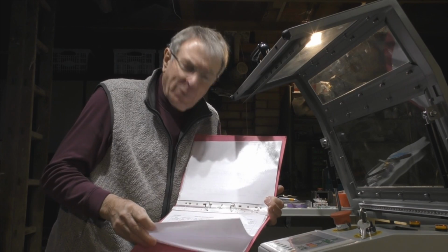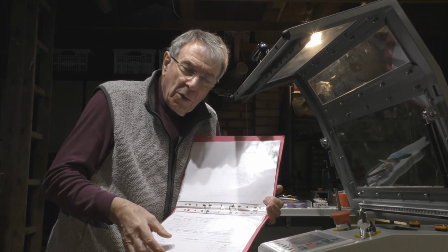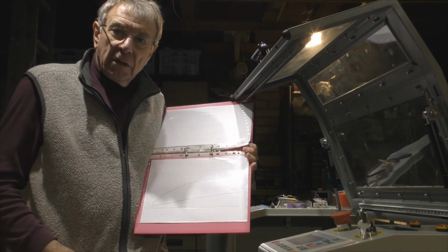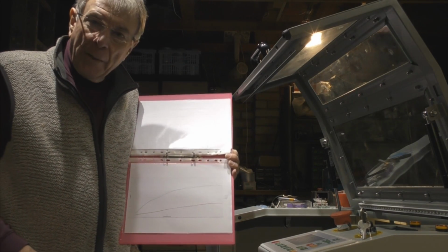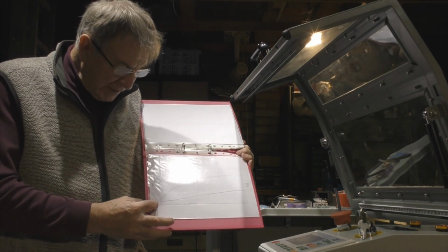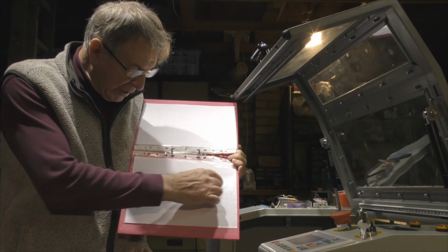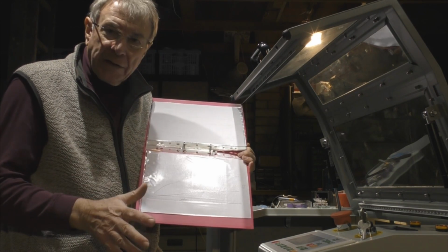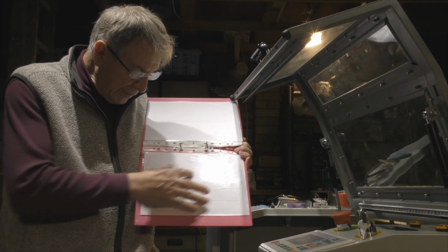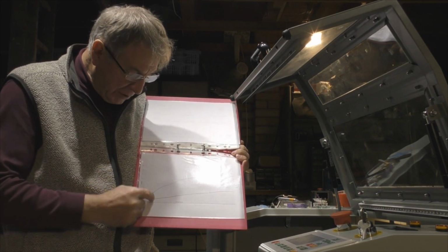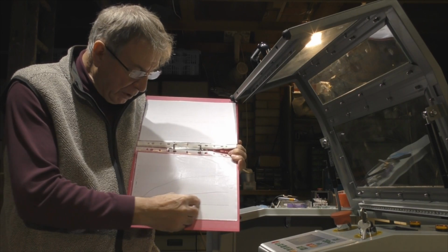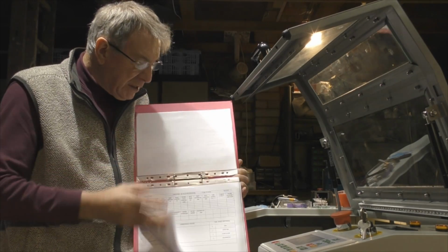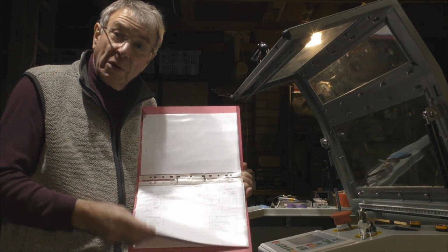So how do you overcome that problem and make your results meaningful? Well, you can't fully protect yourself, but you can protect yourself to a reasonable extent. Good advice would be to see about a power meter of some sort so that you can physically measure the power coming out of your tube to generate this calibration graph against percentage power. And then if you get another tube, you can draw the same graph and you can work out what the power differences are then between percentage power on a 60 watt tube and the same percentage power on a 40 watt tube. And you can start to adapt and modify these parameters without going through the whole process again.